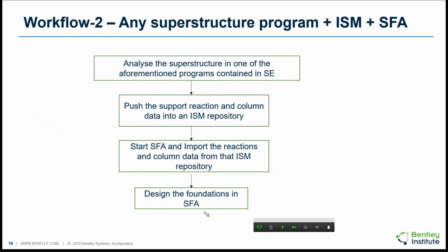Workflow number 2 involves any superstructure analysis program that I described earlier, MicroStran, RAM Structural System, and so on. From those programs, once the analysis is completed, you push the data into what is called an ISM repository.